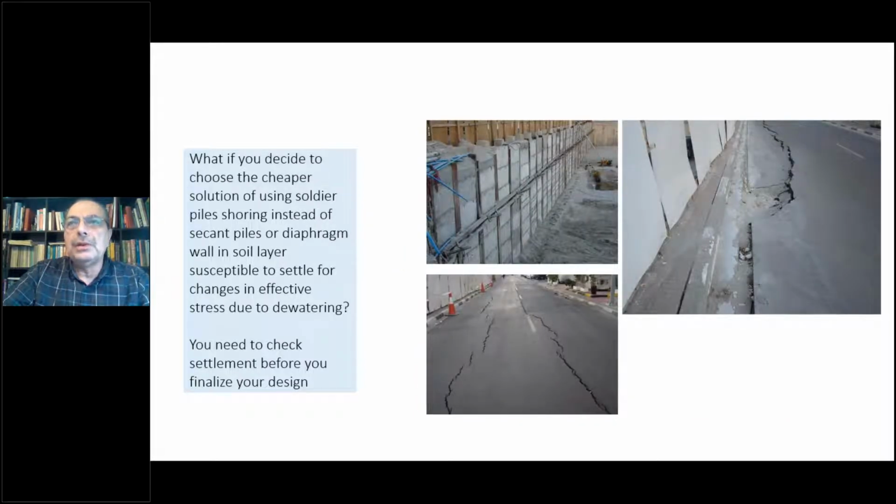Water always is a problem in shoring. Wherever you find water near the shoring, you may have a problem. This is another site with I-beam soldier piles shoring, one row of anchors, and the dewatering system is working. You can see the dewatering system is a well point system around the plot from inside.